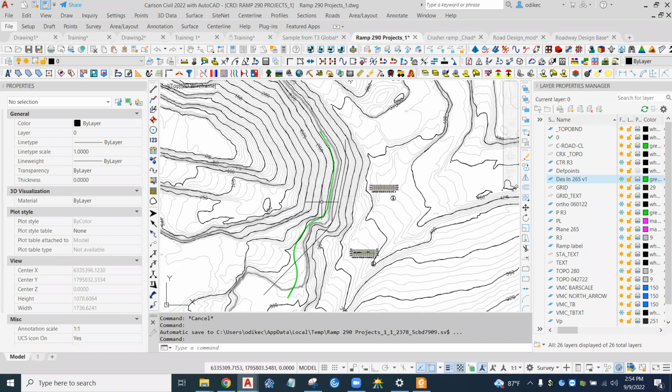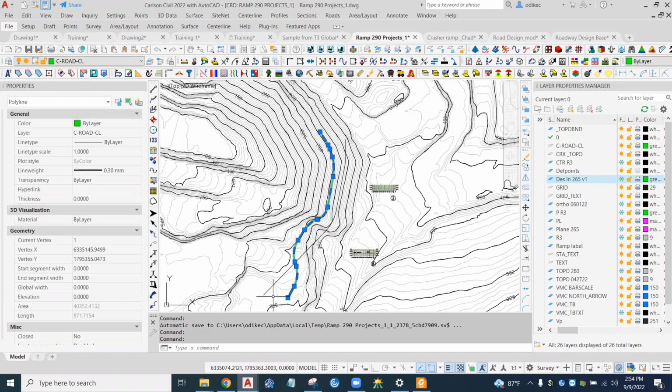So if I called this green line a centerline, and I built that, and I went back into the bank, and I came back out of the bank, then to take that edge out here and tie it back down into that slope, it's going to be even steeper. So what we typically have to do in West Virginia and Pennsylvania on these type of sites is the roads have to be totally in cut. They can't be in fill at all.